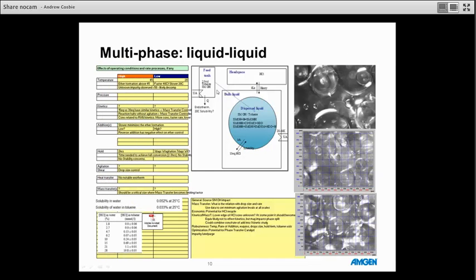And we're feeding our starting material from a feed tank at a given flow rate Q. When it enters the reactor, this is becoming the dispersed liquid phase. And you can see we've actually taken some images from process video microscope and put them right here on the process scheme tab. So we have an idea of what are the droplet sizes, what do they look like across a range of agitation speeds. And then we've captured some of the reaction information here in the process scheme. So these are some mechanistic steps for the desired reaction as well as the undesired formation of this ether impurity.